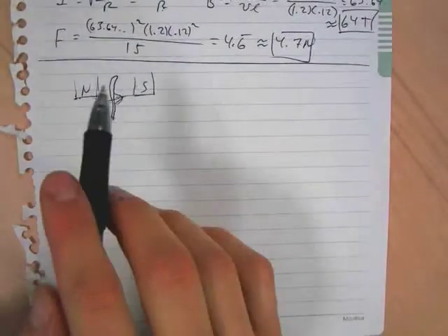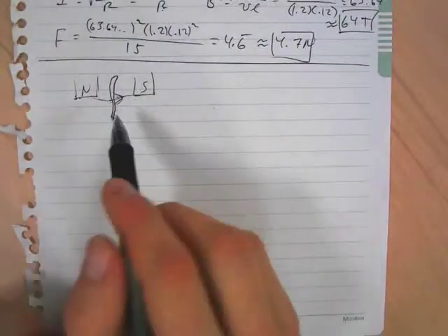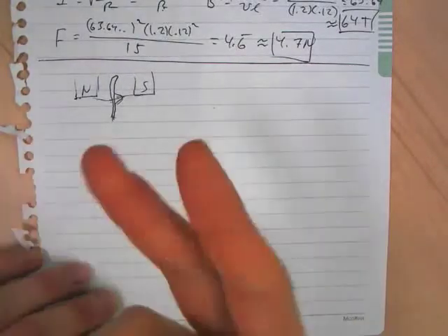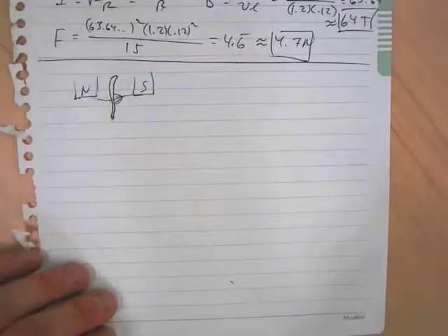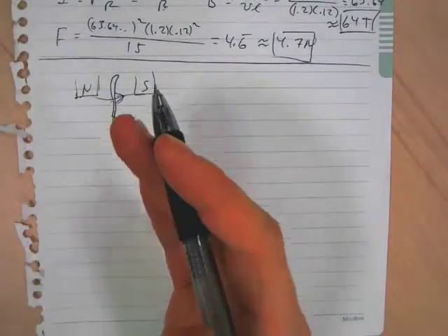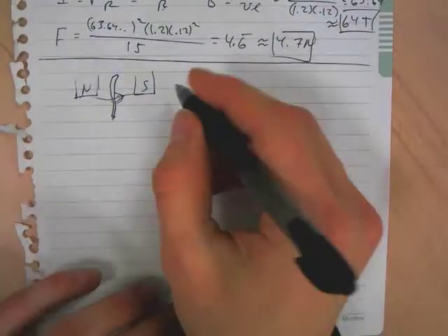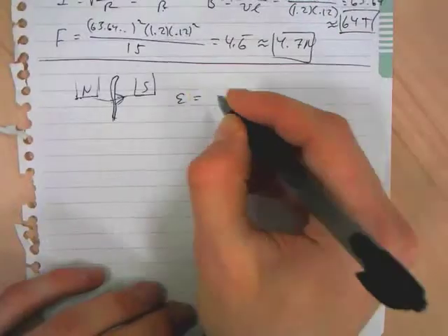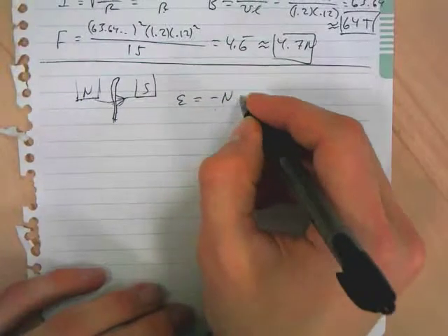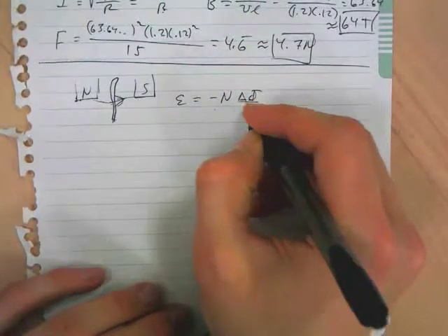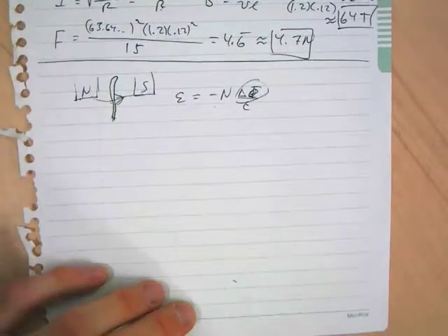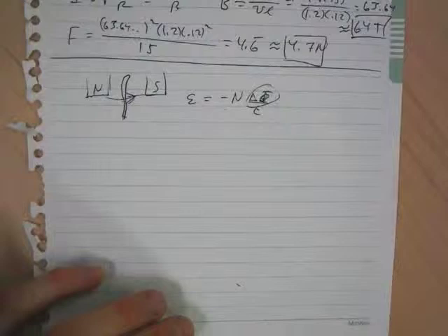And there is a constant magnetic field, but what happens is that this loop is twisted. It rotates, and that rotation generates the changing flux. So we know that the EMF induced in the coil is minus N delta phi over t, and the delta phi turns out to be a sine wave.